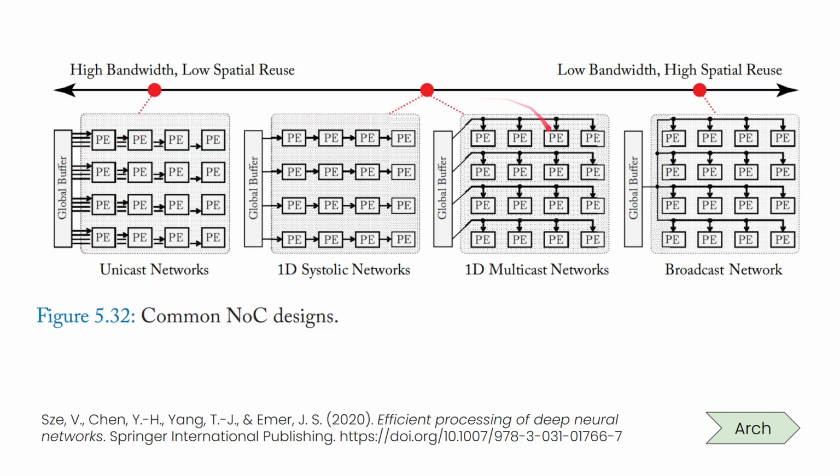As you can see here, you have different diagrams. These different diagrams have different arrows on them, and the arrows represent wires. The collection of wires that connect different processing elements together controls how data moves from global buffers, where we load all our weights and activations, to any particular processing element that needs a weight and an activation to multiply together and add onto a product, a partial sum, things like that.